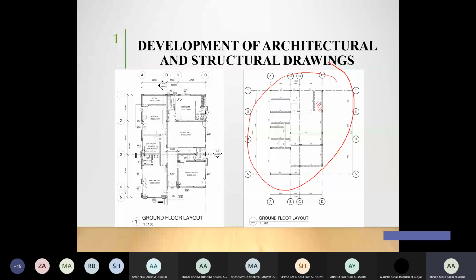Ground floor. Okay, the ground floor is supported by soil. That's why normally we do not include our ground floor, or whatever we call it, slab on grade, in the design. Normally, slab on grade is going to have a mesh only, a typical reinforcement. It's not designed. Why? Because normally the load will be taken directly to the soil.